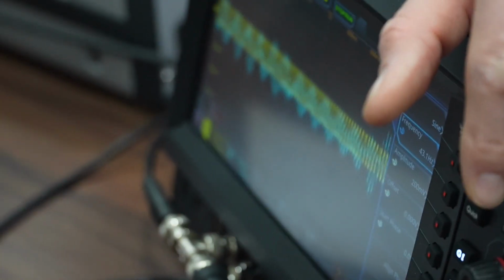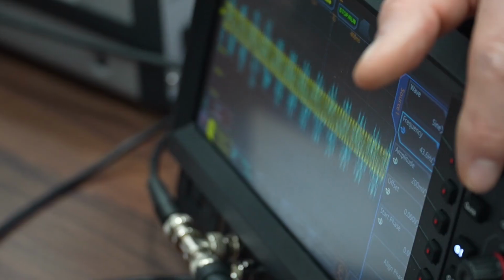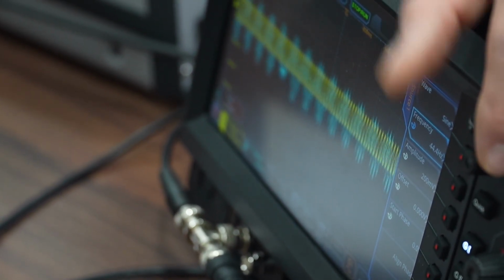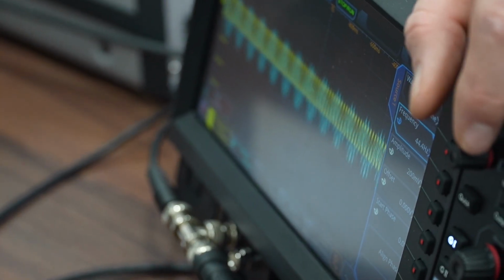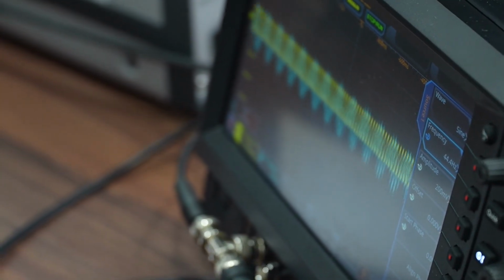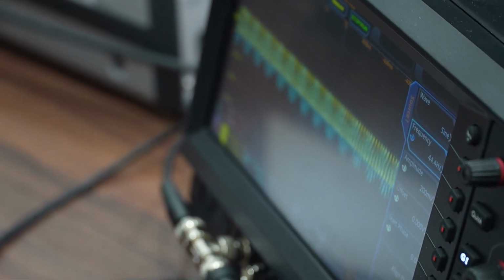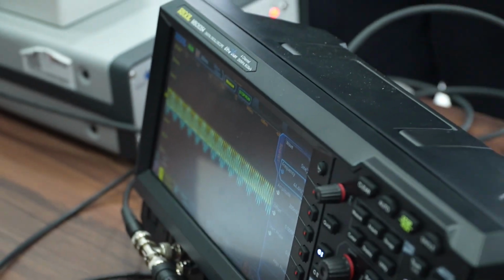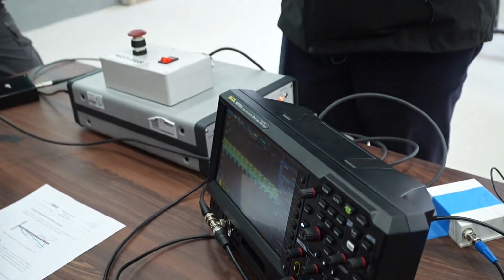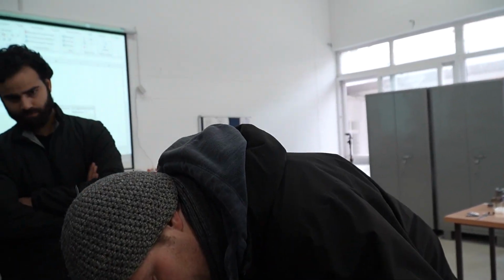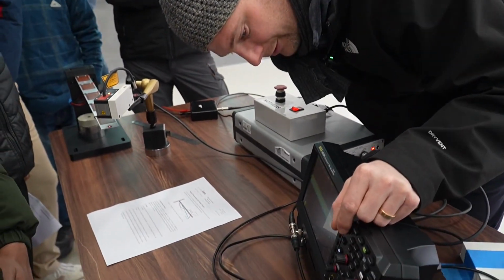Around 45 there was something, but as we increased, there was... So the problem is we always also, you hear this clack clack? Always when I change the frequency, then I give like a small impulse. So I always work on all eigenforms or on all eigenfrequencies. So I also get something towards the first eigenform.